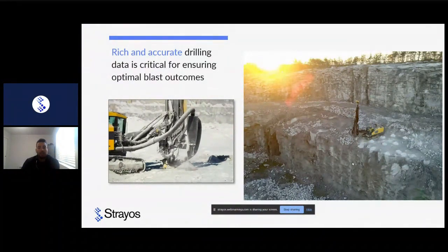The elimination of kicker holes or inclined holes, if possible, keeping faces as vertical as you can. In some applications you might want to keep them at a certain dip angle and drill at an angle, but for the most part, in most applications, keeping things straightened out and getting good drilling data to achieve the best results is what we're looking at here.